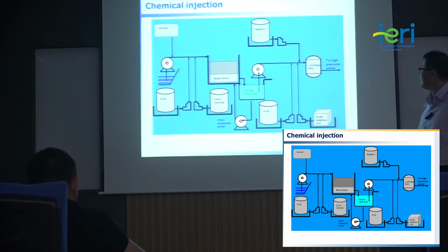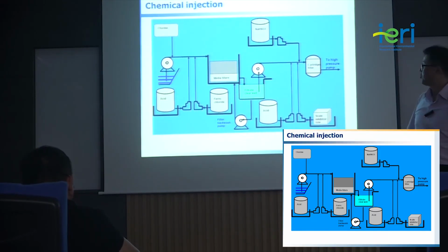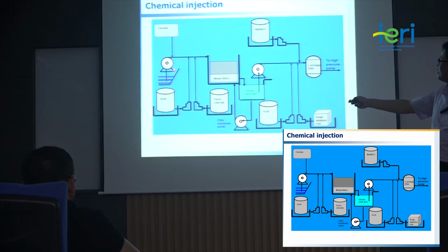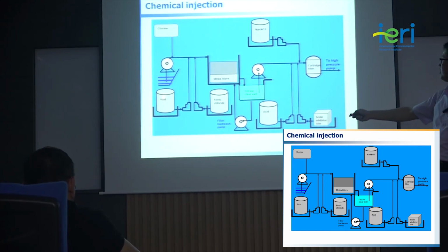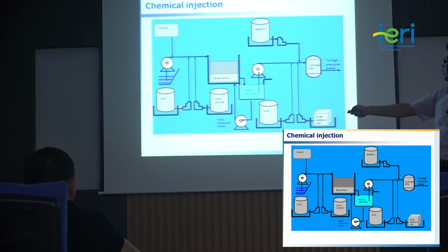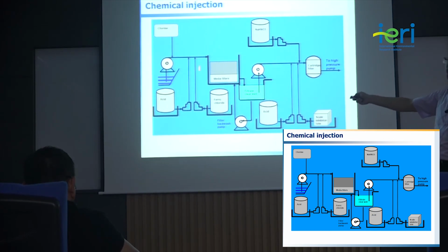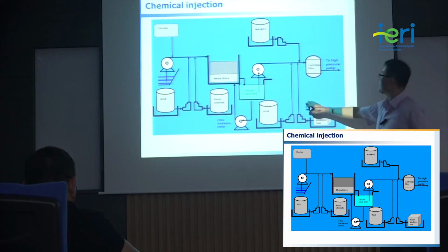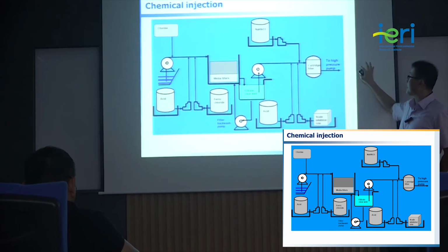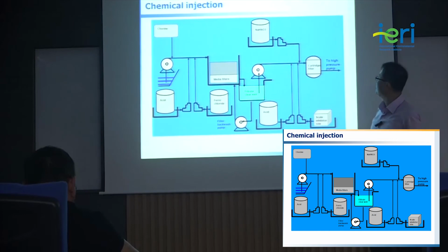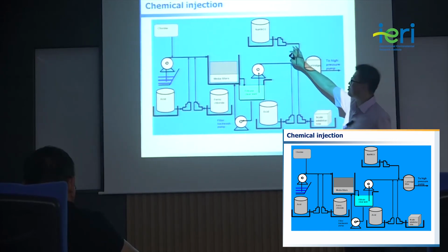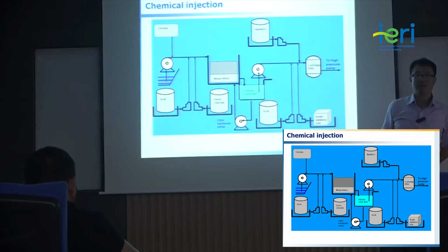And this looks very complex. So intake chlorine, ferric chloride for the coagulation, and scale inhibitor for the inhibition of scaling in the reverse osmosis. And this one is used to remove this chlorine, because this chlorine can break the reverse osmosis membrane.